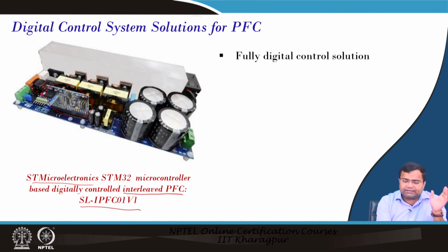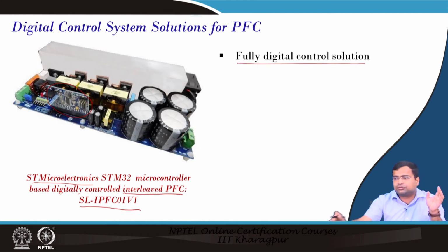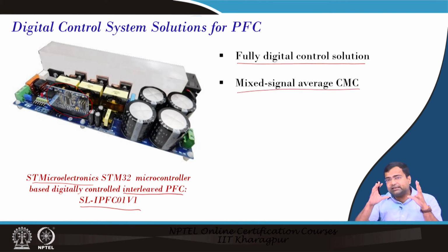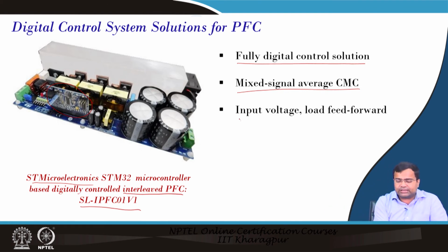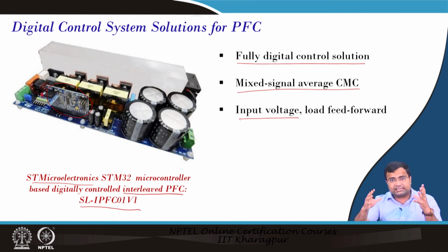So, this particular reference design uses a fully digital control solution, where it uses a mixed signal average current mode control. So, in this course again we are going to demonstrate what is the architecture of mixed signal current mode control. Then this IC uses input voltage feed forward. In fact, input voltage feed forward is necessary because we need to achieve unity power factor.